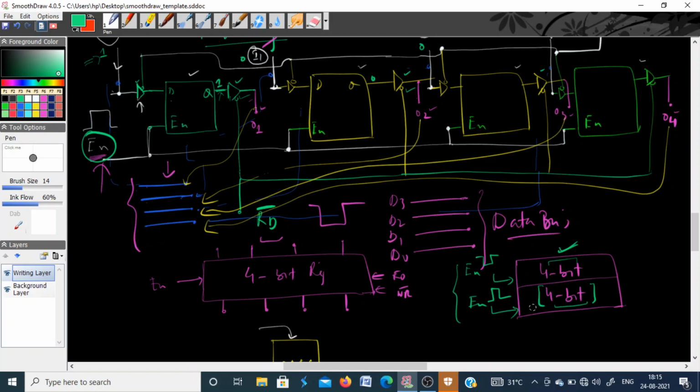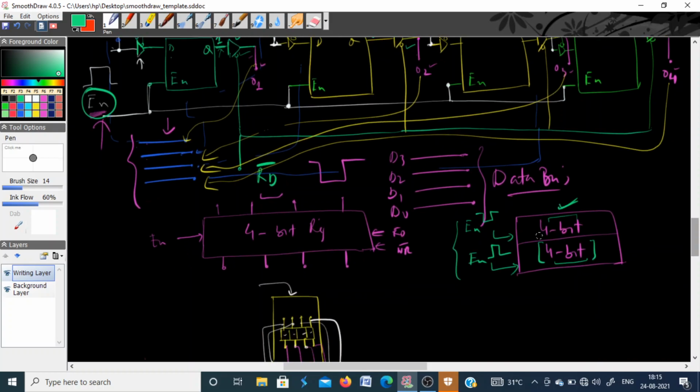So how do you do that? That is done by the address decoder. You have a decoding circuit for that. In this case you can simply have a circuit like this, suppose a 1:2 decoder. It means you have one input and you can generate 2 outputs from it. This is output 1, this is output 2.